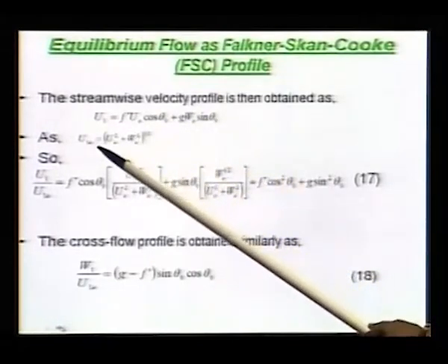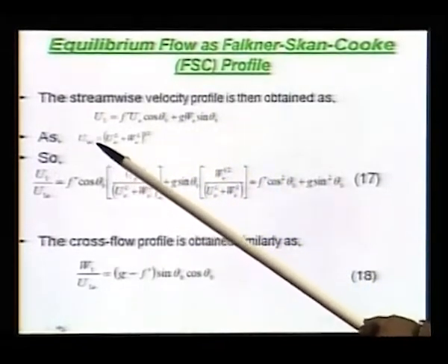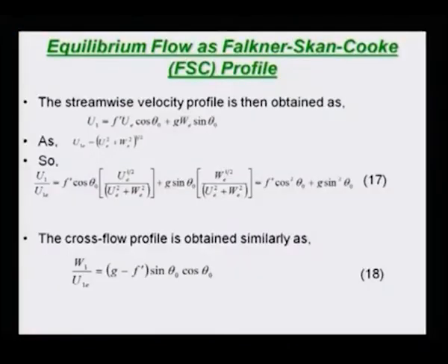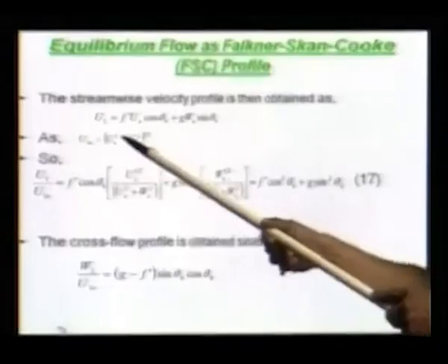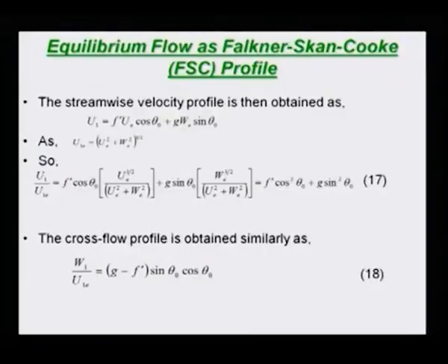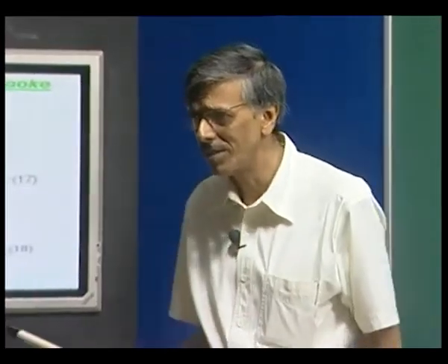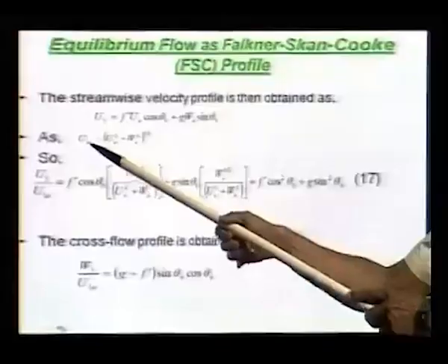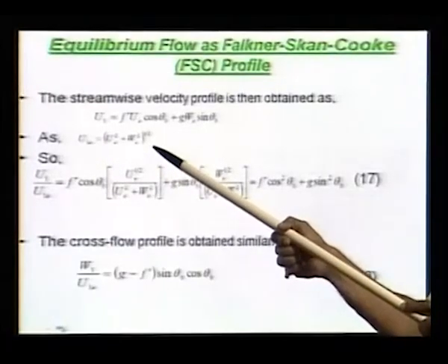And if I define U1e as this, because once you have the wing fixed component and you want to go to the external streamline fixed component, that only has the U1e component. W1e by definition is 0. It will be equal to this, isn't it?